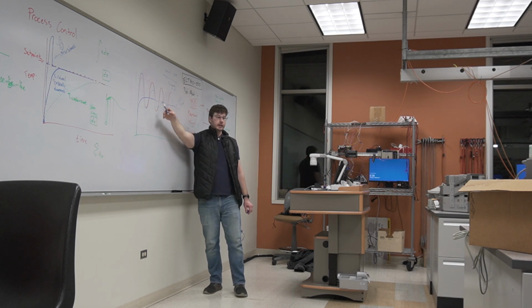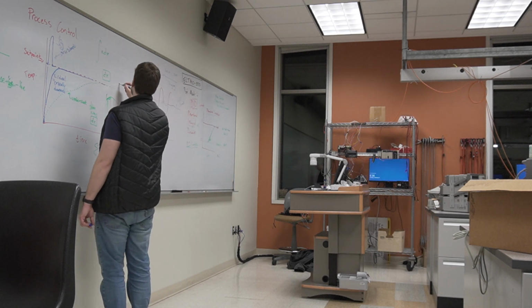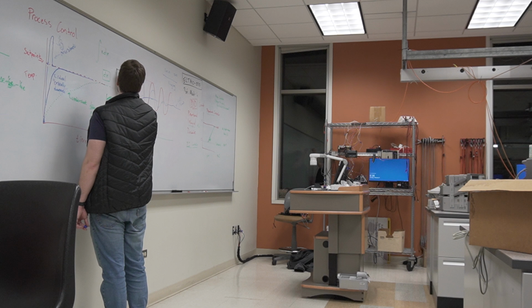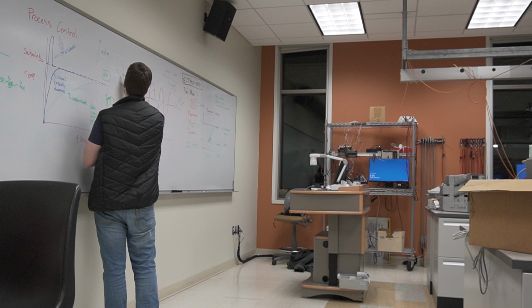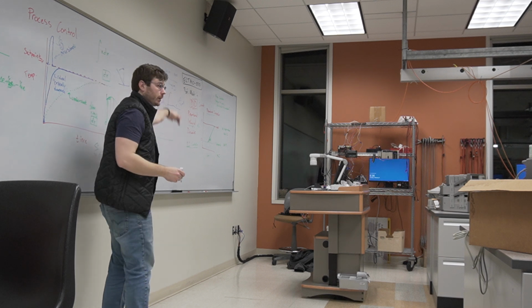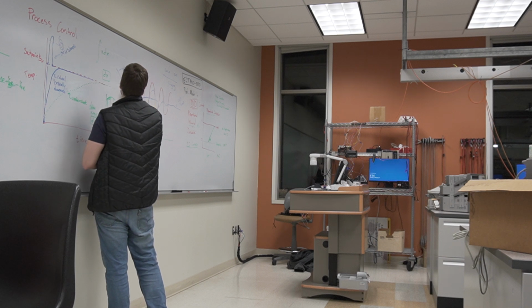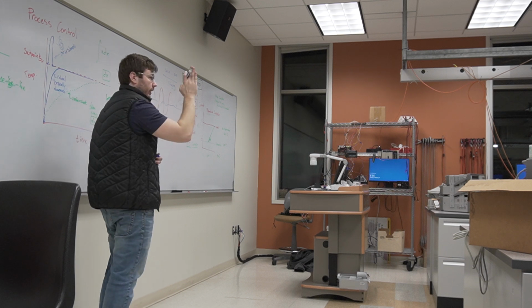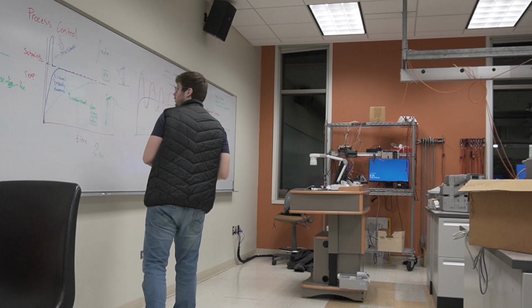So what this might look like for our tilt situation, okay, is if we start off and we're tilted this far, because that's just where we happen to start the system, right? It'll probably want to overcorrect really hard because the proportional controller is going like, whoa, there's so much error here. We got to shove back really hard. I is probably pretty high too. So it shoves back this way, but then it overshoots. So now it's here, and now it has to go back a little bit less and a little bit less, and it'll kind of clock back and forth until it sidles up nice and straight, ideally, in our well-tuned system. Okay.